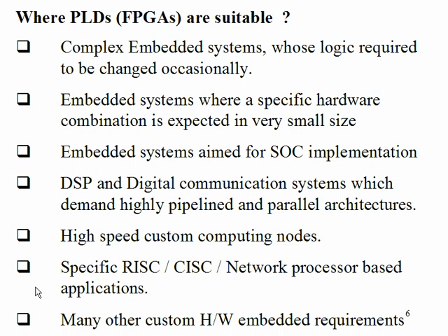So with that clock, the major difference between RISC and CISC is this: RISC will have a smaller number of instructions, point number one, and each instruction does a relatively simple job in a very small amount of time, typically 2 or 3 clock cycles. In CISC, I will have more instructions, many varieties of instructions, and each instruction performs a relatively lengthy, complex job. Got the point?